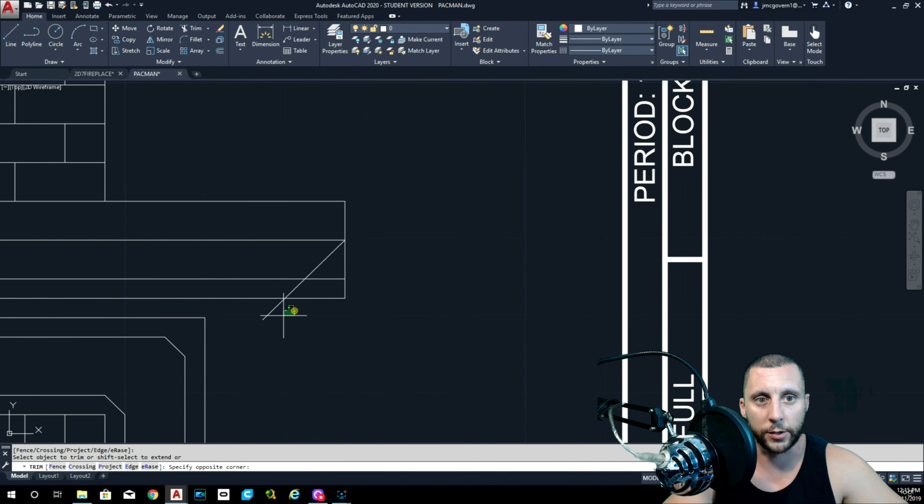All right, so the next thing is we're going to start another one, just like we did earlier with the tape measure. Go right here, slide across, that's going to be 1/8 of an inch. Now if you're just not sliding the right way, then feel free to draw, let's say, one line right off that corner and then do an offset. It is F11, but I've seen some software versions not work the right way. Some funny setting is turned on or off and then it doesn't go. But you can do 1/8 like this, and those will be two reference lines that you could get this next corner.